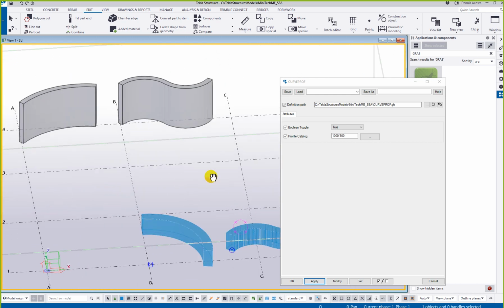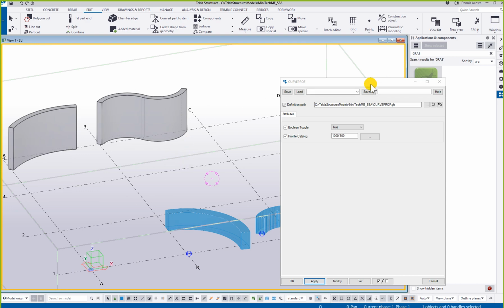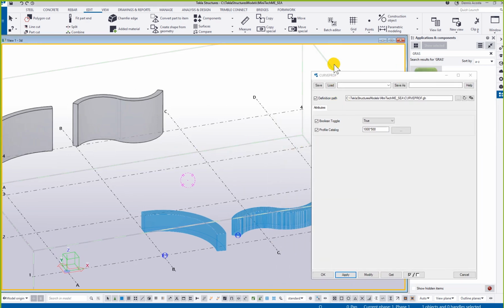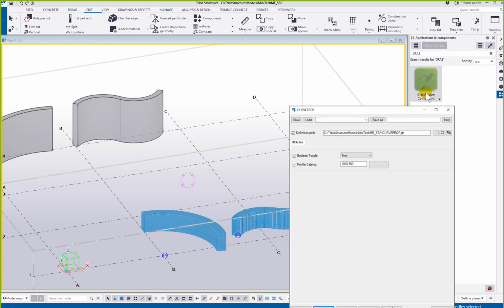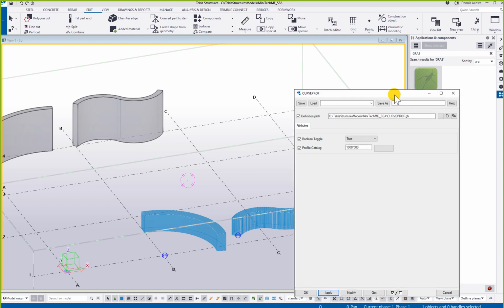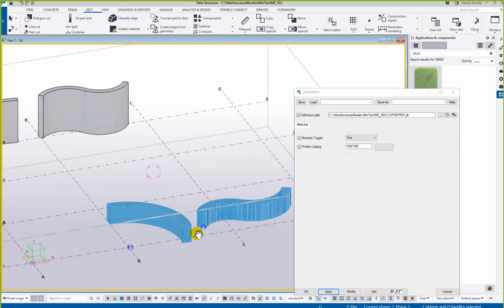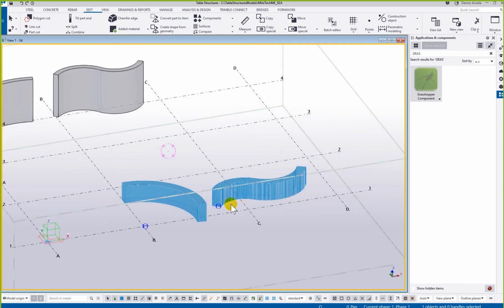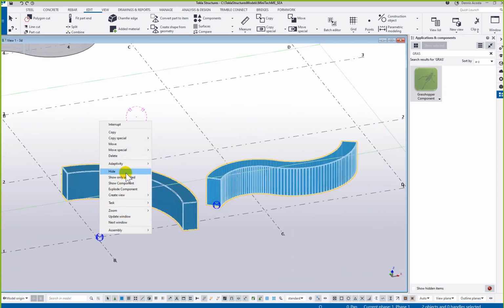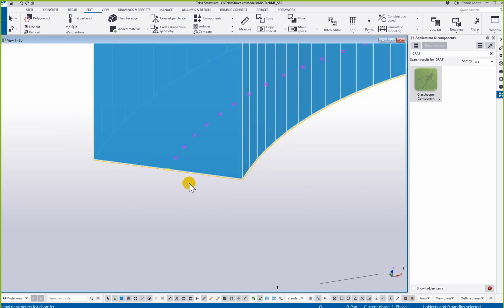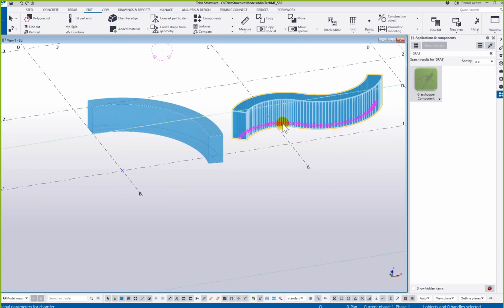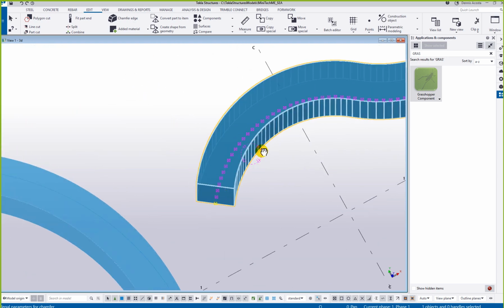So these are two different approaches to creating the curve. Later, if you want to use this curve profile that I made using the Grasshopper component, I can give you this script, and you can just download the Grasshopper component from our warehouse, and then use the script that I have created here. Okay. So once I have this, I can easily explode that one. If you notice here, this one is made of a lot of lines and a lot of points, because it is using the segmented curve.